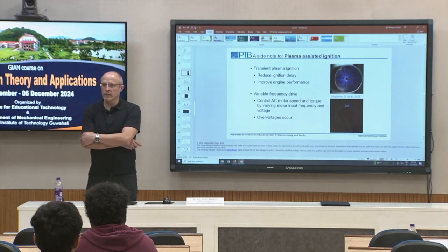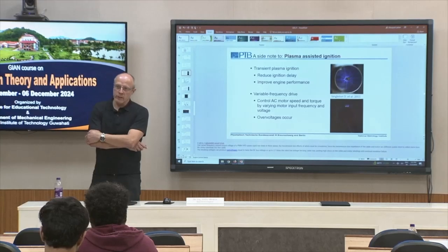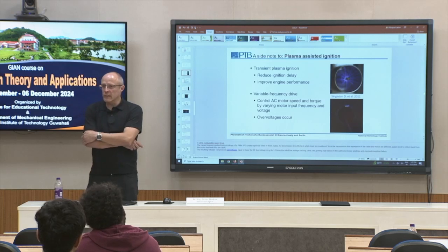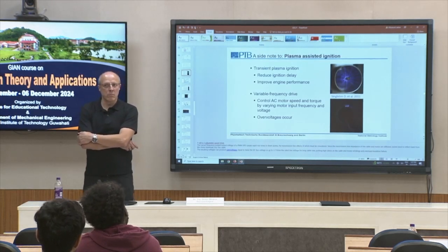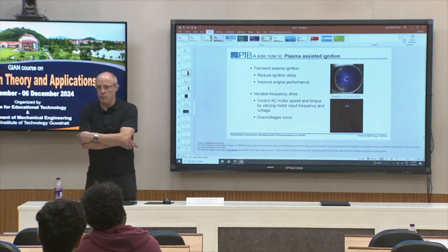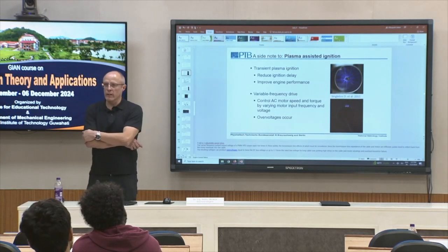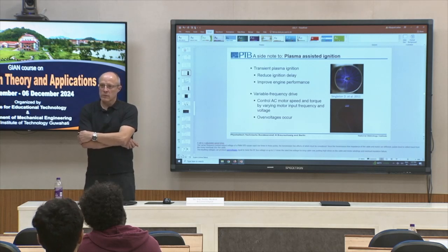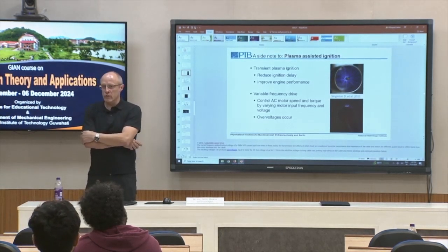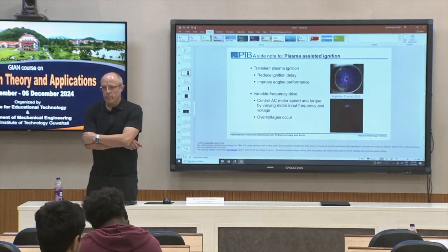You can compare this with the pressure change when a combustible mixture is inside with an ignition event taking place. So you should be able to separate compression from the pressure change due to combustion with this non-ignition event in the background. Yes, that can be the solution.